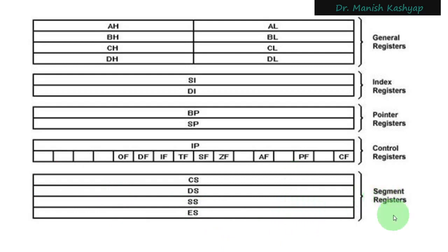Now, in combination with these segment registers, we use index registers. For example, we are working in the data segment. Suppose the actual physical address of the data segment is 50000 in hexadecimal. The last hexadecimal digit has to be 0, which it is in 50000. The last digit is already 0. So the data segment register, which is internal to the microprocessor, will keep 5000 in hexadecimal in itself. The remaining 0 is implicit. So this data segment register will contain that particular address.